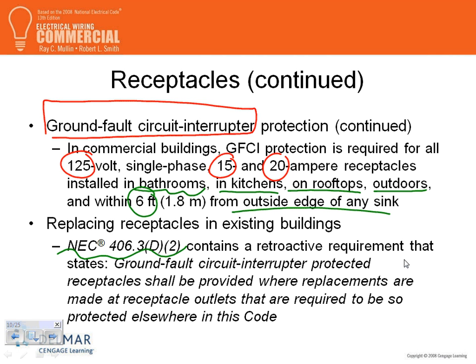Any question, guys, about this? I can't emphasize enough, this is non-residential. I'm not going to review the residential with you guys. You're very familiar with where in residential we need a GFCI. There is one word, guys, almost common between all these locations: wet. Any wet location, almost anywhere, you need a GFCI.